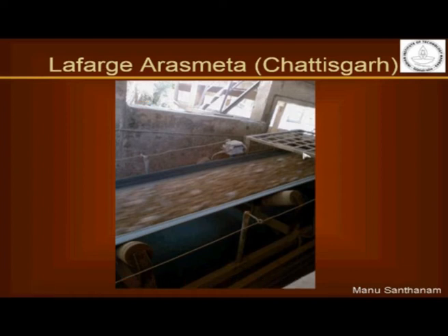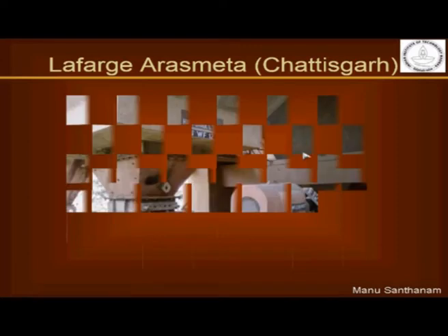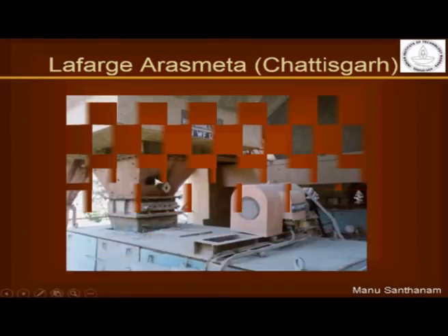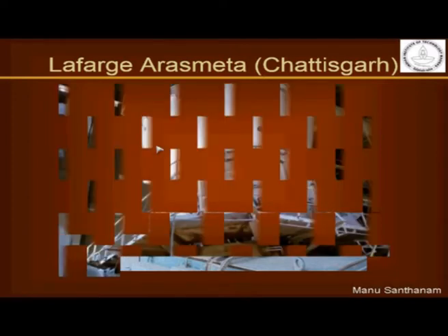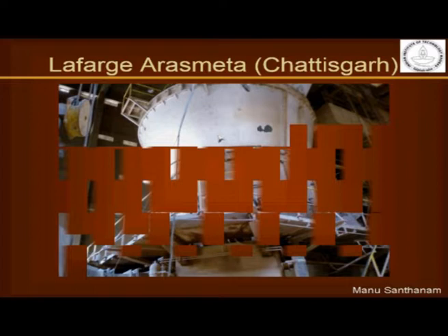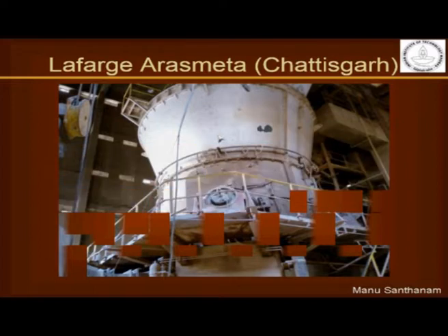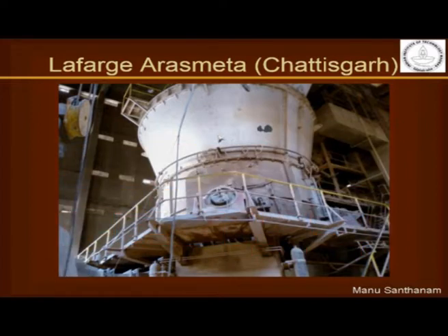a grinding unit or a pulverizer where the limestone will be ground to a size which is small enough to mix well with the clay. So now this is the grinder. This is the unit which is grinding your raw material and converting it to a very small size. Another picture of a different grinder, because the crushing equipment is typically separated into different parts. You have a coarse crushing and then you have a fine crushing to ensure that you finally get a very good mix or very good blend with the raw materials.